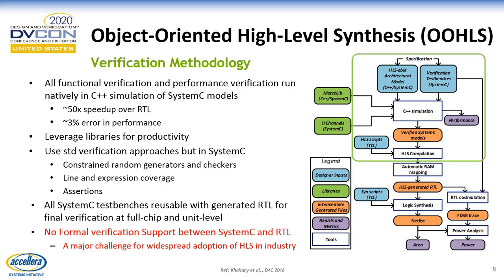And I would like to mention that a major challenge today in the widespread adoption is lack of formal verification support. There are limited tools available that can do C++ to RTL formal verification. However, a full-fledged system-level tool for SystemC to RTL is still a work in progress and is open for research. As a result, we performed all the RTL verification, both at the unit level and chip level, by reusing the SystemC test benches, and this enabled us to reduce the design effort in the verification time.